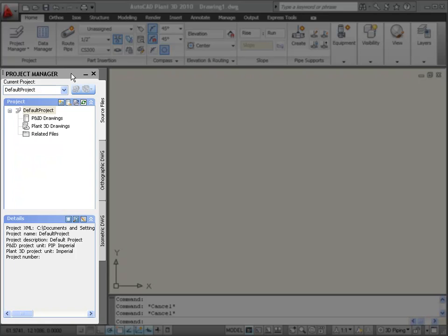The starting point for managing projects is, of course, the project manager. In the introductory video, I talked about how AutoCAD Plant 3D organizes drawings into projects and how the project controls the pipe specs available, allows piping connections to cross drawings, and allows project-wide data viewing, exporting, and importing. The project also controls the annotation styles available, the data fields for each component type, Isogen customizations, the organization of objects and data manager, and so on.